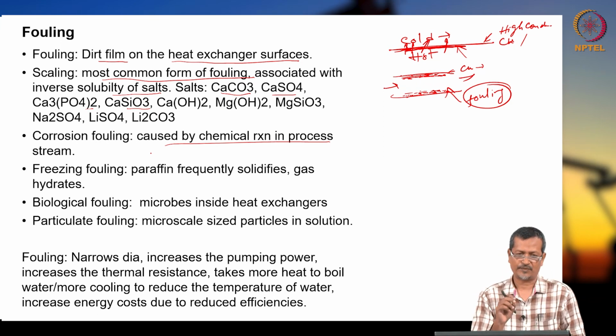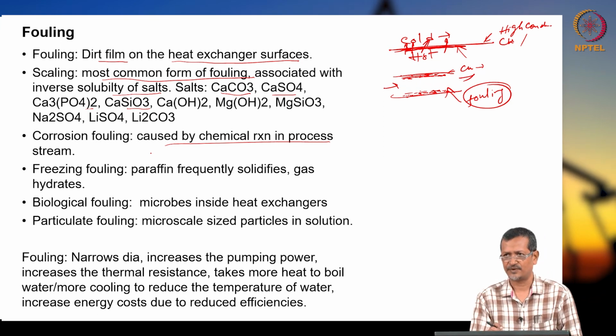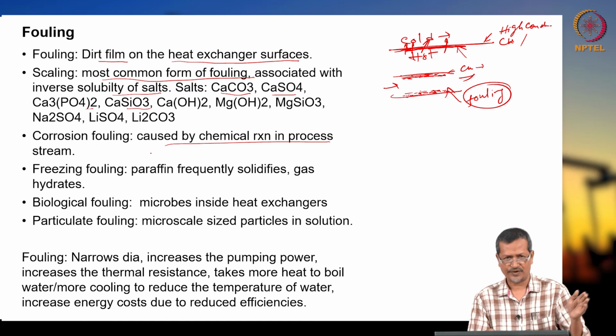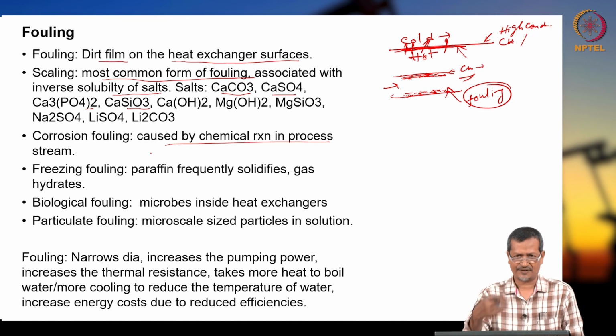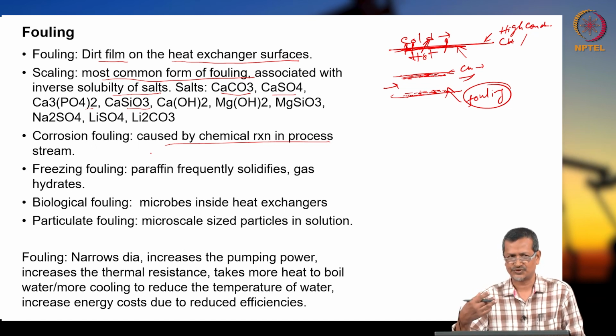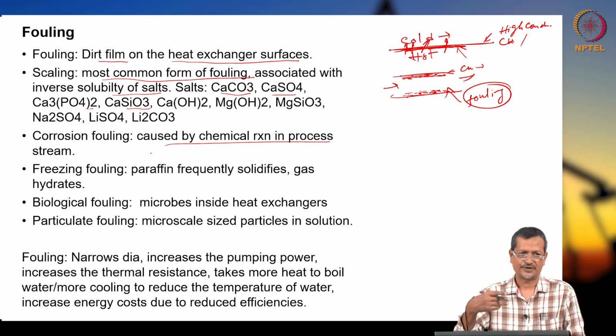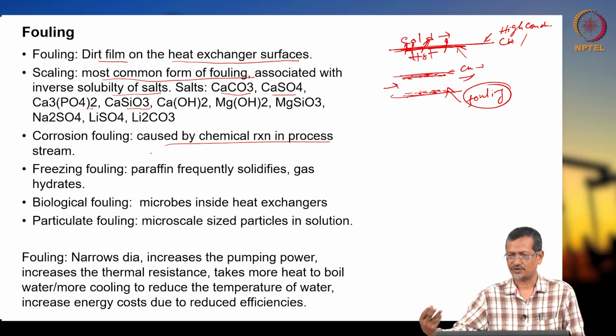And regarding fluid flow, one property you have to remember every time is that fluid wants to flow in a smooth, straight path. So if you are giving any restriction, it will be creating lots of turbulence, it can create erosion, cavitation. Okay, so that sort of issue will be coming.